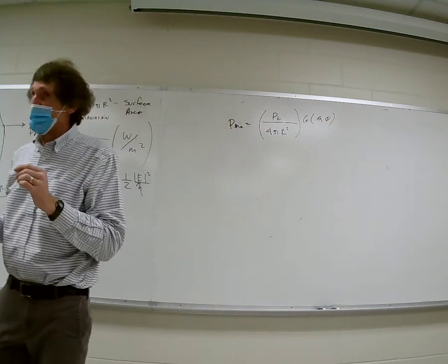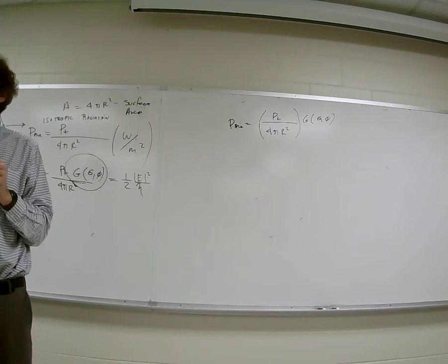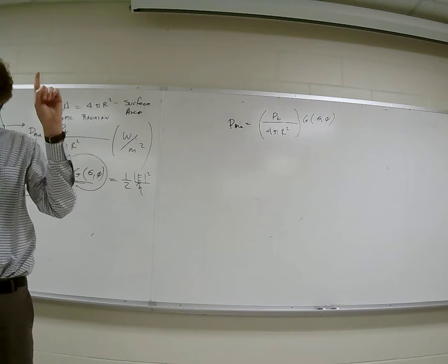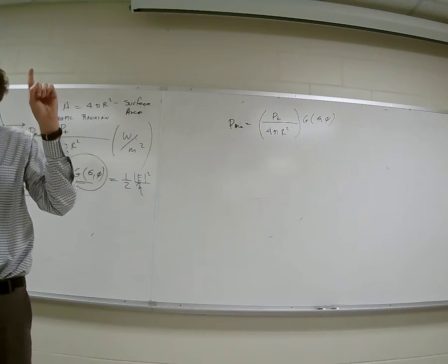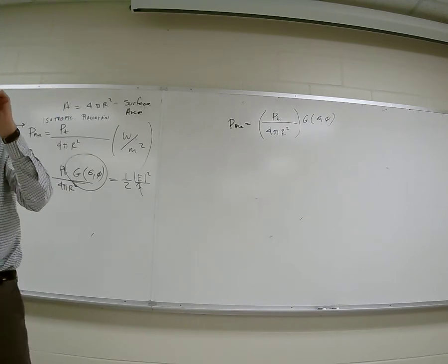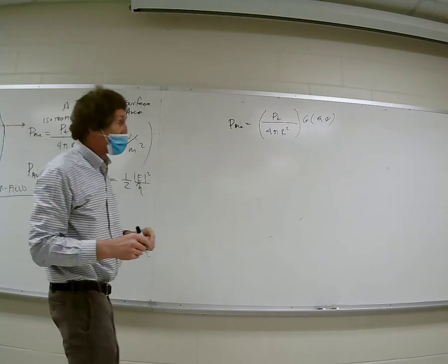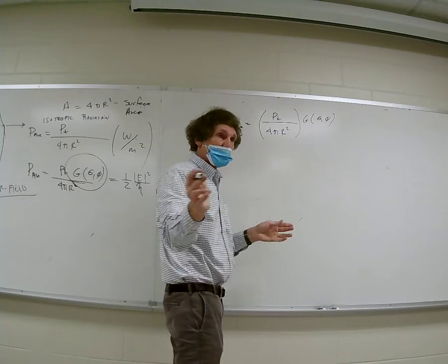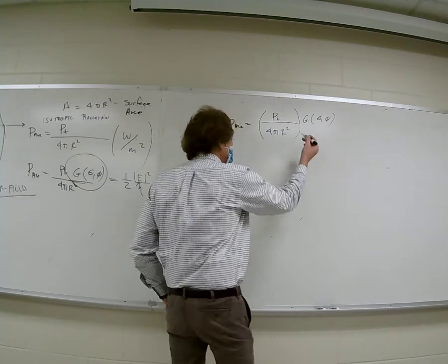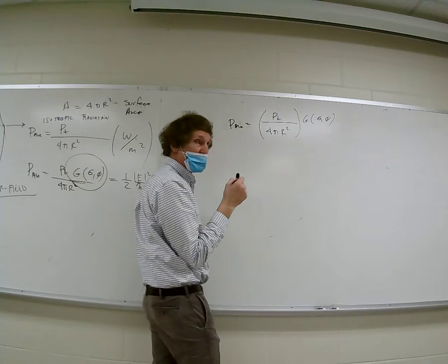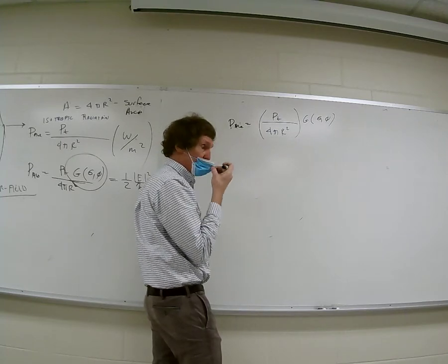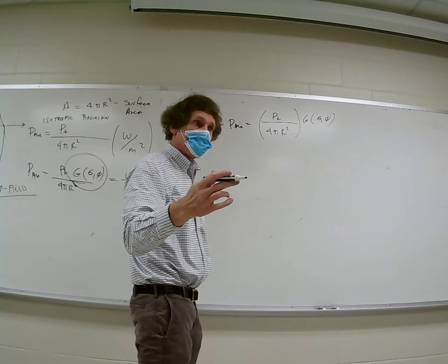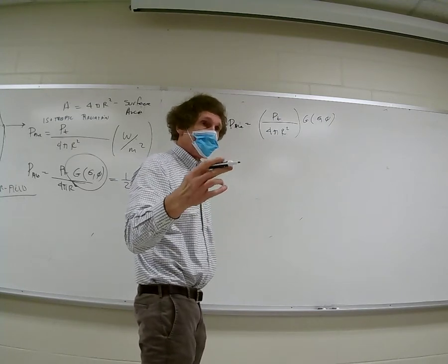For an isotropic radiator, for something that has really no effective gain, it's 1, right? You all see that? It would be 1. It can't go less than 1 for its total average value, because that means less power is coming out of there than if you had an antenna. But the gain itself tells you how the power is really dispersed versus angle. Gain is really the same thing as how the power is dispersed. And Wentworth talks about normalized power, but gain is just as easy to understand, and usually it's done in dB, but it doesn't have to be.